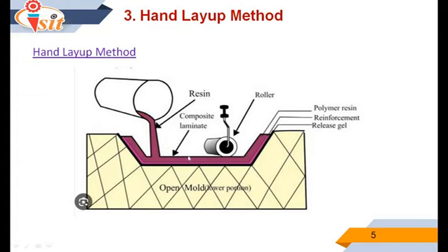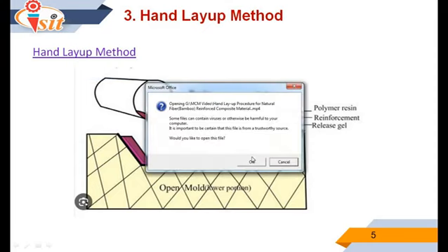So we have to pour the resin on the reinforcement, and then apply the resin thoroughly on the laminated sheet, and in the latter part we have to apply a compressive load, just so that the resin gets penetrated easily into all the void spaces in the fiber reinforcement sheet. Okay, so here we will see how, through the hand layup method, the laminates are going to be manufactured.